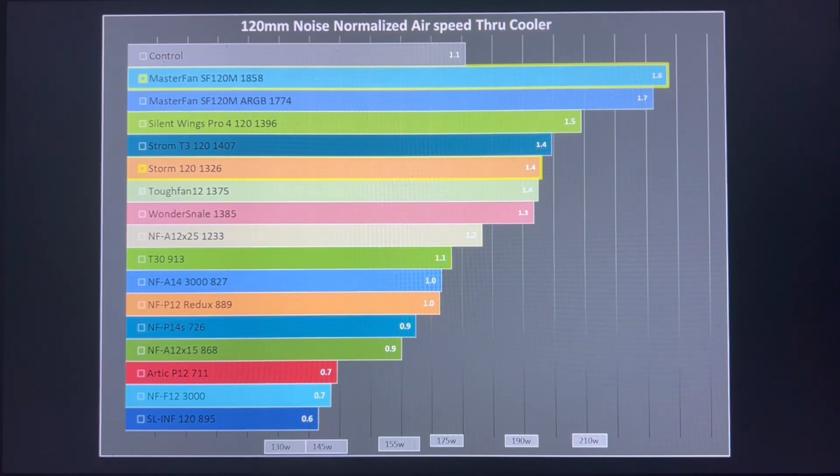My CPU's maximum draw is 250 watts, and that was at something like 2.8, 2.9, maybe 3 meters per second of airflow, just as a reference point. So I know I don't have any data points over here at 1.8 on this particular graph. But what does this mean for your air cooler? Well, if you don't have the same one as me, you can't use this data directly.